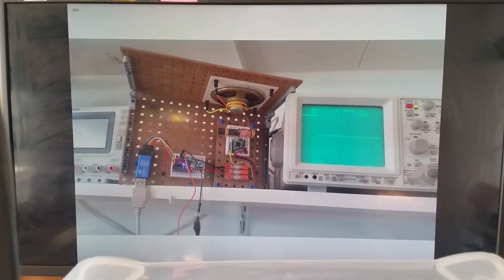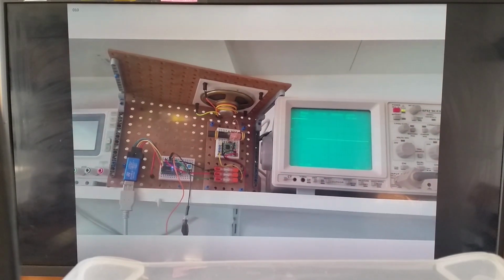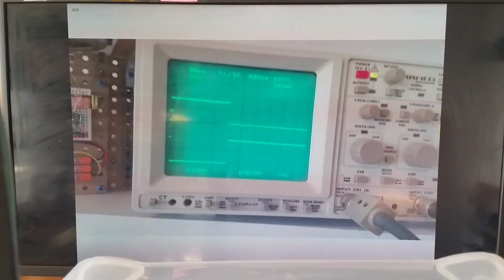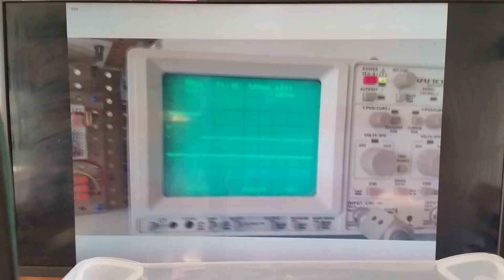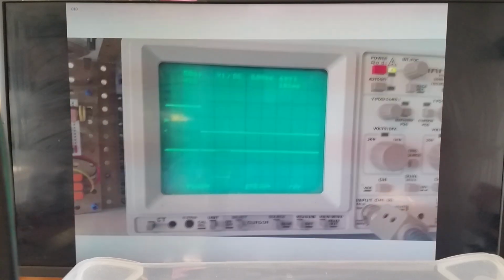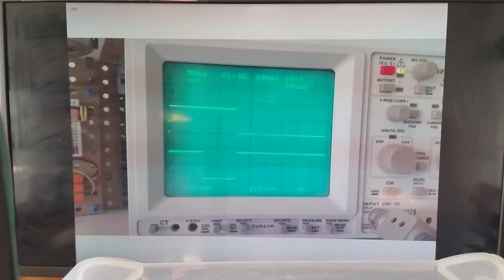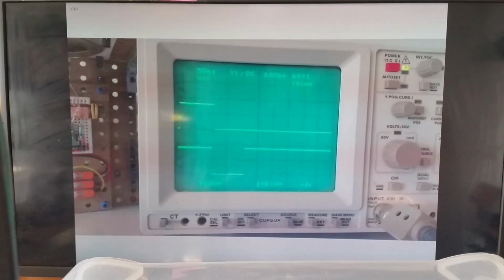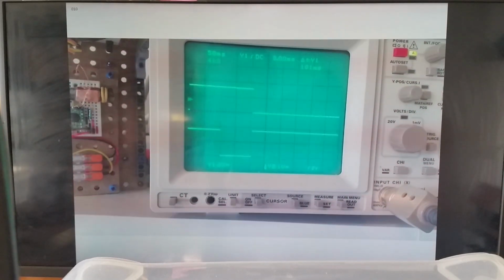Many times on my oscilloscope I see a new bit receiving, but the onboard LED does not light up. The upper channel and the lower channel are both 2 volts per division. The upper channel is the incoming data. The lower channel is the onboard LED going on and off. So it doesn't make any sense what I see here.